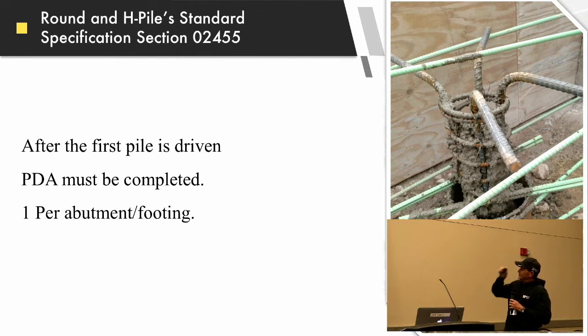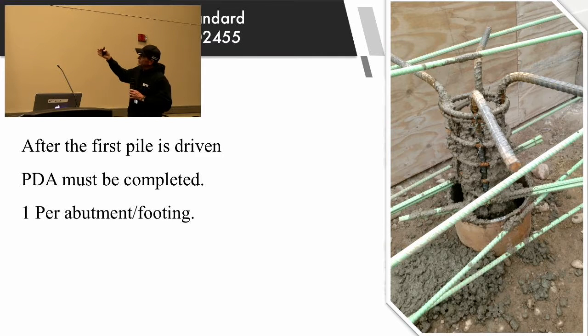This in here, after the piles have driven, and this kind of takes up a couple of deals. Rebar placement in the round pile. As you're placing the concrete in that pile, they'll run a solid tremie down through the center of the rebar to get down below the rebar, so you don't get segregation and everything going down into your pile. As they're coming up, you need to make sure that cage is centered as perfectly as you possibly can in the pile.